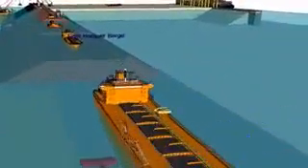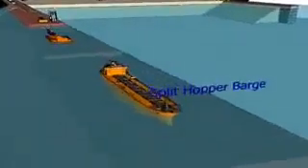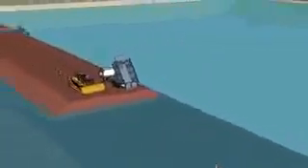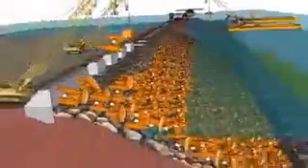The breakwater is constructed using core rock, rock armor, precast armor units and geotextile. The core rock is placed using split hopper barges in deep water and by lorry tipping and dozers in shallow water where the risk of slippage is minimal. The precast armor units are placed using crawler cranes fitted with a real-time visual aid system that enabled 70 placements per day. The wave wall is cast in situ in 6-meter-long sections.